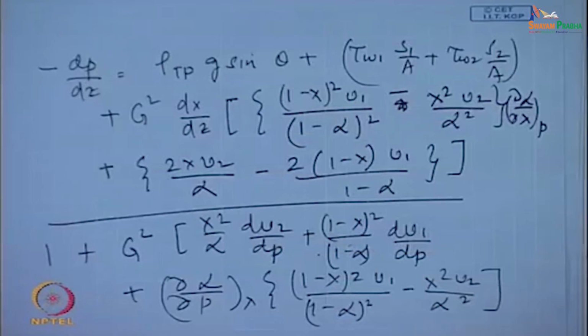What else can vary with pressure which we have not considered here? Something else can also vary with pressure if you see this particular expression. See, I cannot give you much time to think, that is the tragedy here. I have taken dx dz to be constant, or in other words, x does not vary with pressure. When does it happen? It happens under ordinary circumstances in absence of flashing. So, in this particular case, we have assumed that flashing does not occur.